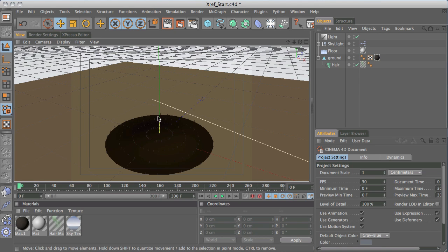Now, I know I've already got one built, and that could have been either purpose made for this project, or from a previous project, and my top tip is brought on quite nicely by that: model everything to scale. If you build everything to real world scale, whether it's imperial or metric, doesn't matter, you'll know that all of your assets are going to work with each other.